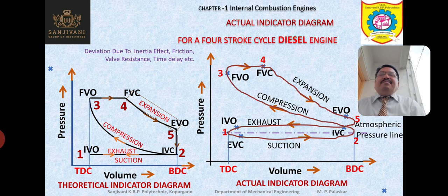Then there is always some time delay. You will find that the engine rotation speed is very high, and even if the valve opening starts at a particular instant, it will keep on opening till the valve opens fully. You will find that the rotation of the crank is something like 10 degrees, 20 degrees, 25 degrees, or even 30 degrees. So though the valve opens quickly, still during the quick opening of the valve there is a sufficient rotation of the crank, because the speed of rotation of the crank is quite high, and this will induce the time delay. Relative time delay is induced in the various processes like the opening and the closing of the valves in the working of the IC engine.